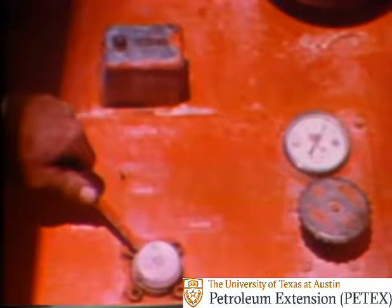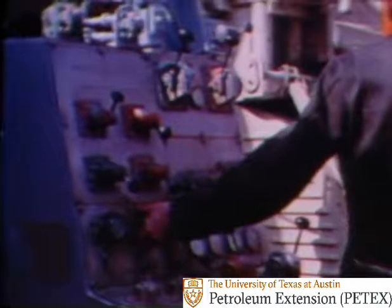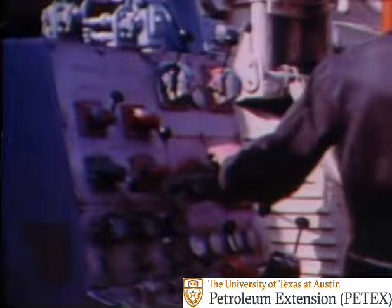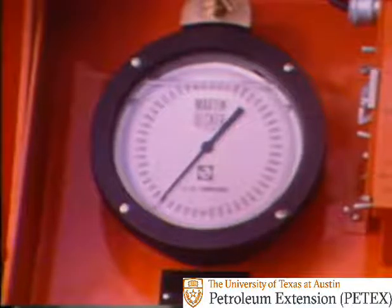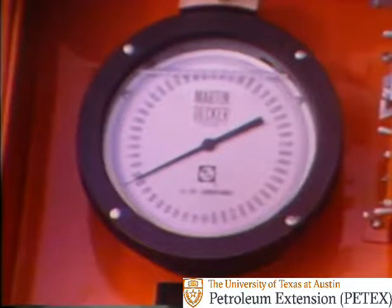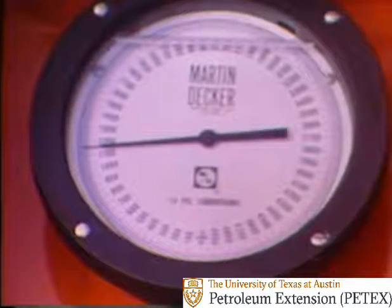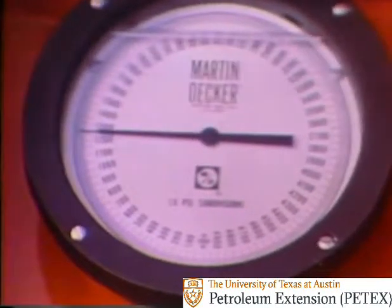The first circulation is started by opening up the casing choke and simultaneously bringing the pump up to the preselected reduced speed. The drill pipe pressure will increase too and is held constant at the figure obtained by adding the preselected circulating pressure to the recorded shut-in drill pipe pressure. The increased constant drill pipe pressure is maintained by adjusting the casing choke.